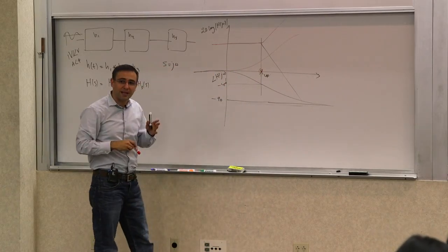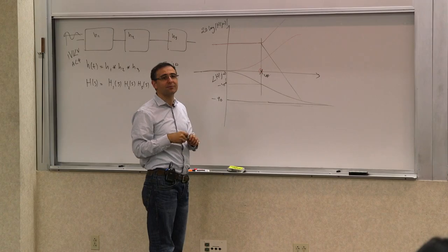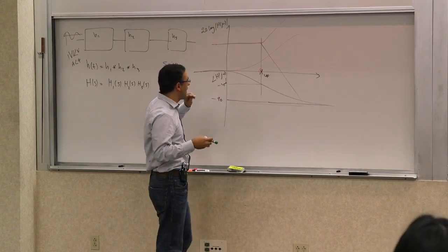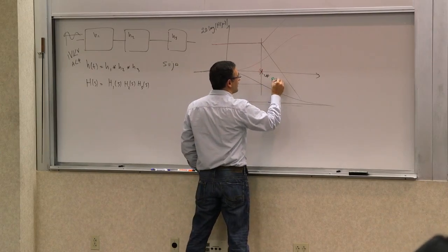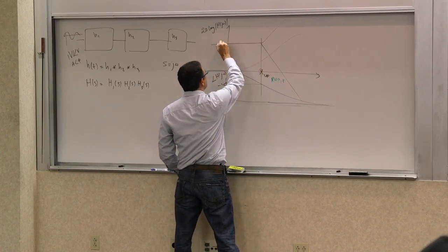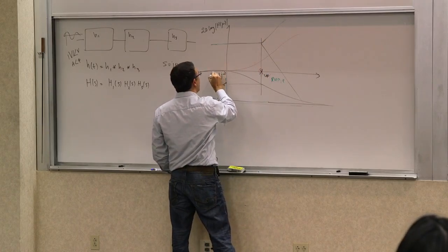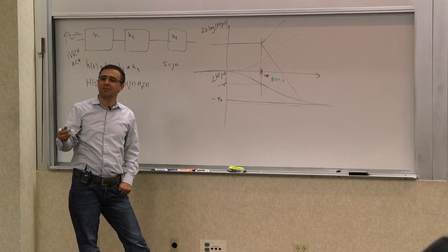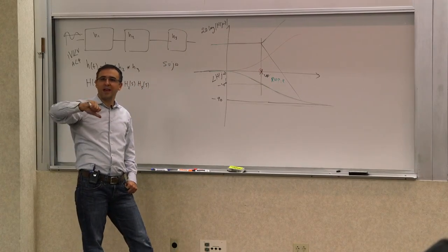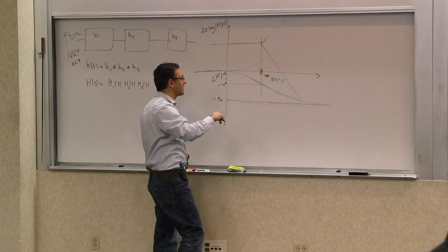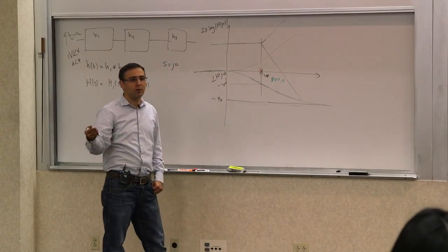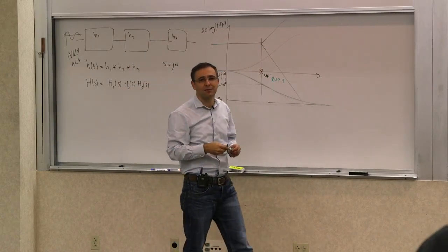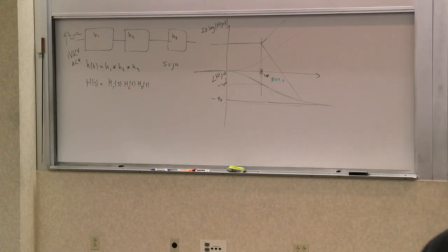Now, the interesting thing to pay attention to is that right half-plane poles and right half-plane zeros particularly are doing certain things the same way and certain things differently. So a right half-plane zero would have a similar amplitude, but its phase behaves like a phase of a left half-plane pole. So its amplitude is the same, whether it's left half-plane or right half-plane, but its phase switches. And the same thing is true about a right half-plane pole. The magnitude part of it would behave this way, but its phase behavior is like that of a left half-plane zero. So that's for that.